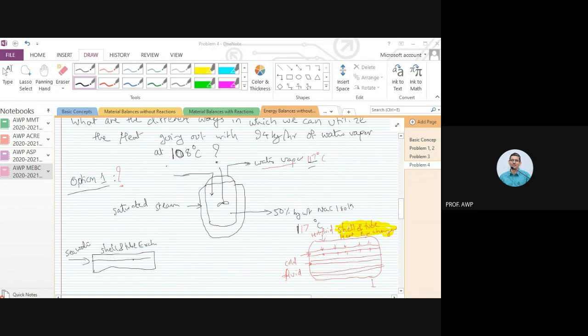It will go inside the tubes, get heated up, and take this water vapor and make it condense outside the tubes. Don't you think that is possible, Smith? Yes, sir. So this water vapor will condense back into liquid water, and the cold seawater will get heated from 30 degrees centigrade to maybe 80, 90, 100 degrees centigrade.